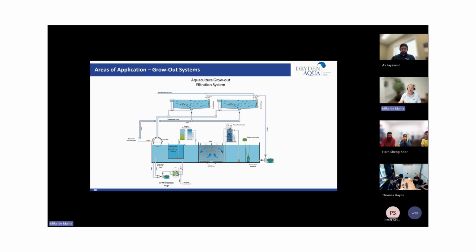So this is, again, a concept that, coming from our experience both in aquariums and aquaculture, we would say would work very well using the AFM filtration media, because the last thing you want to do is have any organic load in your denitrification system. It just compromises the denitrification system and creates problems for pH and the possible release of H2S into your system. Okay, and again, whether you use oxygen concentrators, nanobubbles, Venturi systems, or Spice cones, or whatever it is, those will always be required, right? Okay.